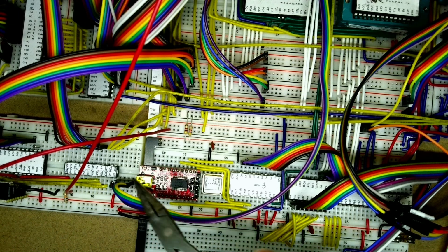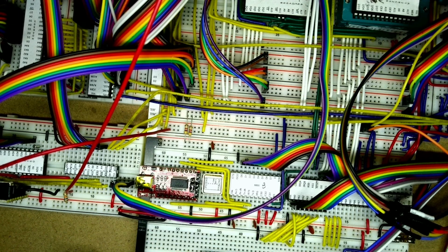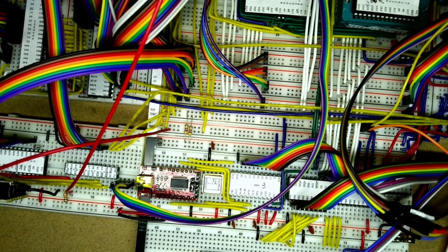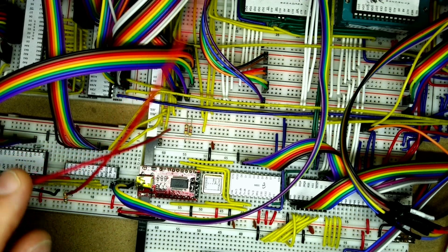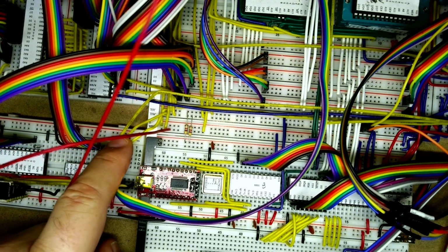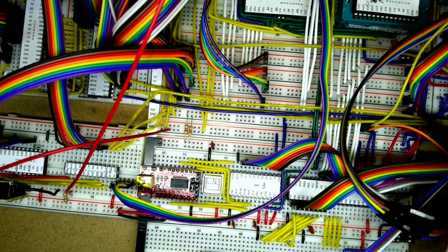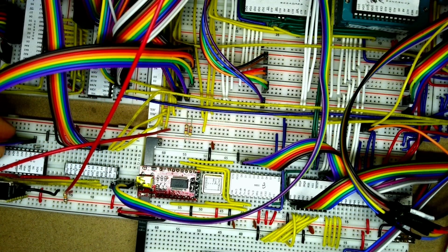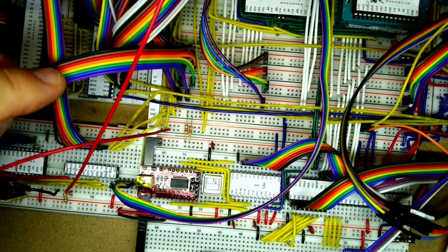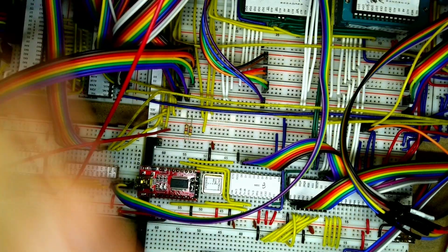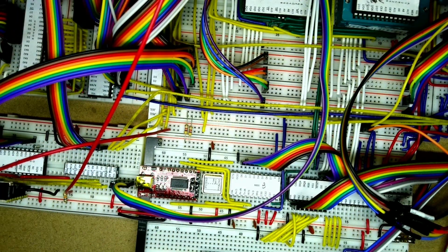It's a little bit rough and ready at the moment because when we add the IDE controller, then we're going to reorganize this a little bit anyway. So we've got the reset line, we've got our IO read, IO write, and this is the IO A19, A12 line coming in from the other decoder. We've got our data lines and all the various address lines coming from here and here. So the next thing we need to do is to update the BIOS.